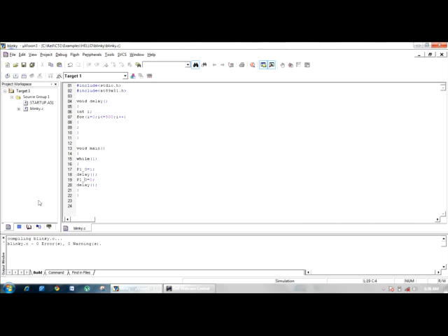Now you get build the project. Now you get blinky.c, 0 errors and 0 warnings. So no errors, no warnings. Now the next tab found over here is build the target. We have to build this file. Click build. You get 0 errors, 0 warnings again. Now click rebuild. You get 0 errors, 0 warnings again. So with that, it shows that your project is pure and complete in all respects.